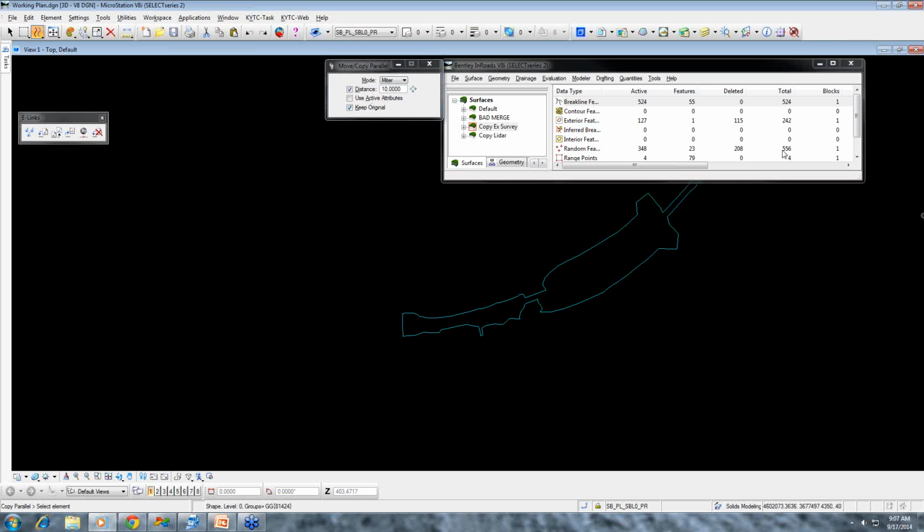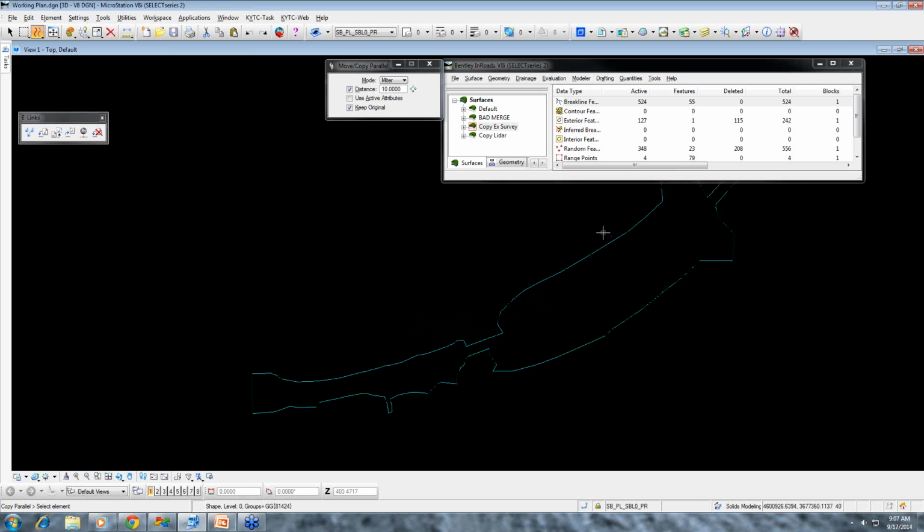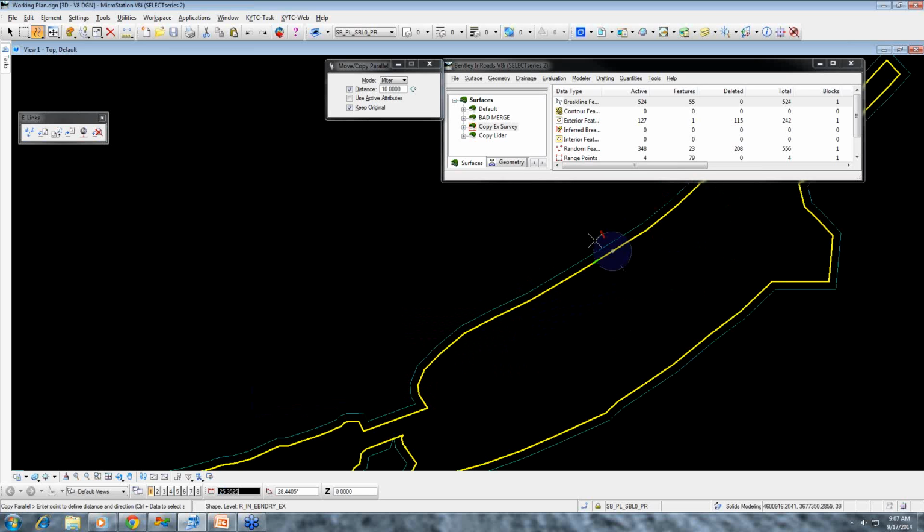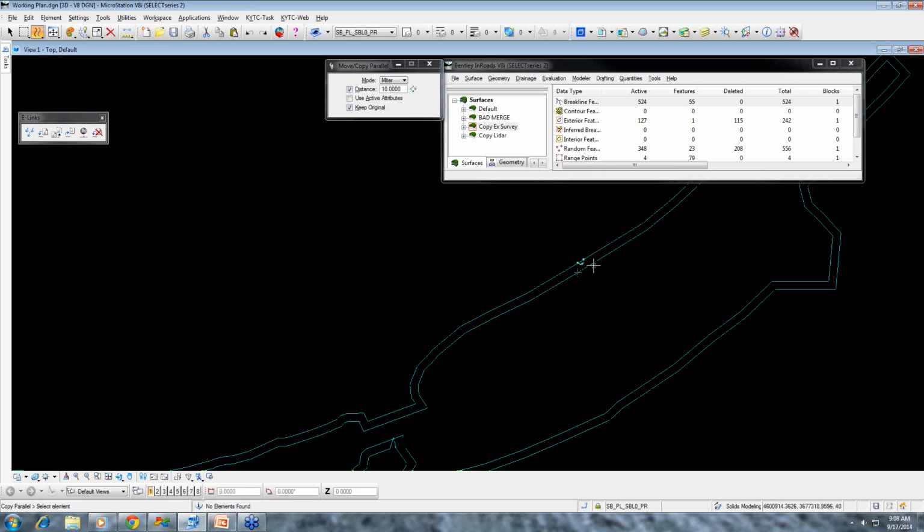And we want to keep the original. I do that for myself so that I know that the boundaries have changed. Because I make mistakes, and I just want to make sure that the boundary has actually extended that 10 feet. So I'll actually select the boundary and offset it 10 feet. Left click again, and it'll be offset. And then we right click to get out. So we actually now have a boundary that has been offset at 10 feet.